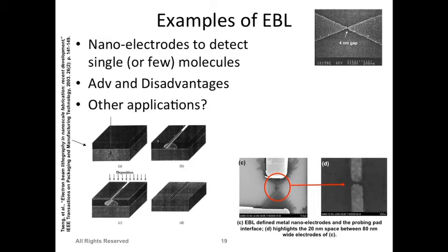You can also deposit certain material in a small area. If you use an ion beam, and do the whole process in some chemical vapor environment, which can deposit material if you give it enough energy, then we can actually focus on a small area in the chemical vapor environment. Then that material will be getting deposited very locally in that area, if that is desired for some reason.